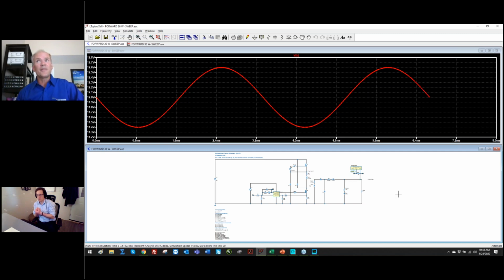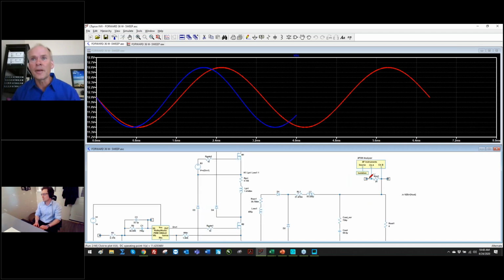This is now possible, and it's faster to do this, even though it's fairly excruciating, than it is to read my 200-page book, generate the small signal model, do the plots, and then figure out why it doesn't agree with what you're measuring in the lab because you put filters on it that don't count. So this, even though slow, is going to be a time saver. Sometimes I like how slow LT Spice goes, because I can learn. I can look at these waveforms: oh, look, I'm shifting the injection here. I can look at the other point on the waveform, here's the other signal.